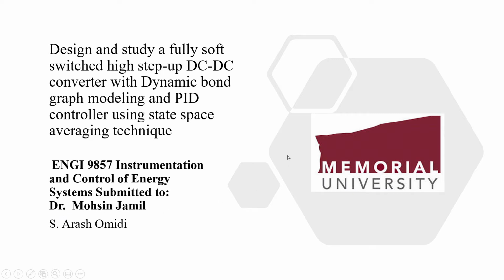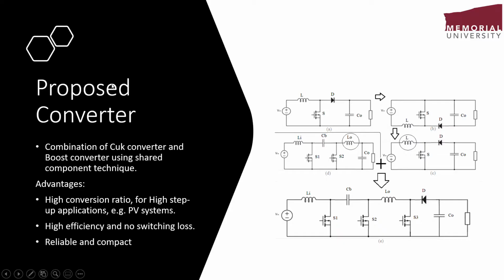Mohsen Jamil. Here we have the proposed converter, which is a combination of a Cuk converter and a boost converter using the shared component technique. Here we have a boost converter. It's a conventional boost converter. Here we change the place of the inductor and diode. Functionality is still the same.